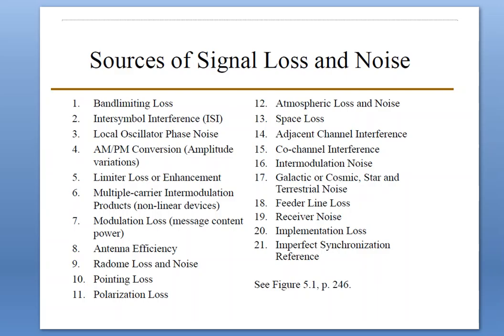They can either cause a loss in energy or be responsible for noise injected into a link. Here we consider passive intermods. They are caused by multi-carrier transmission signals interacting with non-linear components at the transmitter output.